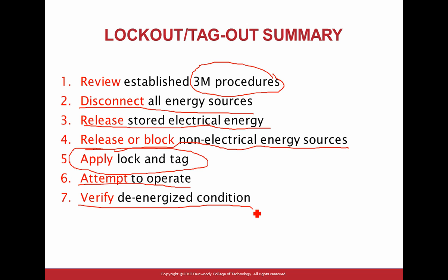Now the equipment is dead. Now it's completely in a safe working condition. Does that make sense? De-energization. But what people forget is to test your equipment. That's why when you get your meter, the first thing you're going to do is make sure that it's working. Verify it's working. It's not just make sure, verify. By plugging it into a 120 outlet and put it in voltage, AC, not DC, and measure it. And don't put it on amps and measure voltage.